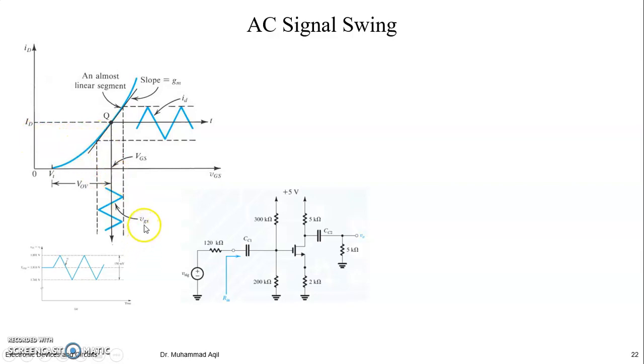So the transistor will be behaving according to how much voltage instantaneously I have on my gate to source, right? And it will provide ID accordingly. And remember, it can provide ID when we have applied a VDS, right? It can create the channel, but current will flow only if VDS is set to some value. In here, it would be in the saturation region, right?